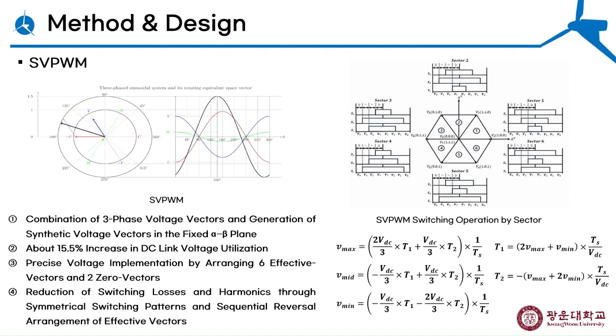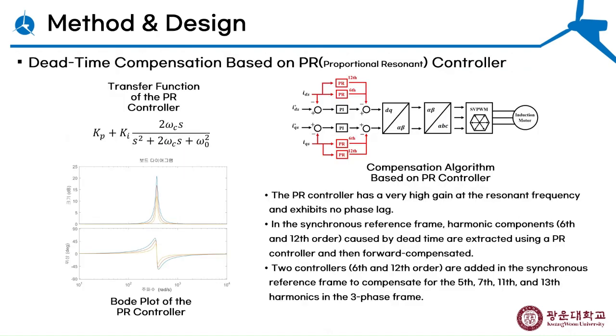Three-phase inverter switching states are divided into active and zero voltage vectors. Zero vectors occur when all switches are on or off, producing zero output. Active vectors occur when one or two phase switches conduct, producing 6 possible vectors that determine output voltage magnitude and direction. The voltage space is divided into 6 sectors, each with its own active vectors combination. Within a sector, phase voltages are classified as maximum, medium, or minimum relative to the DC link voltage, allowing precise calculation of T1 and T2 times for the active vectors.